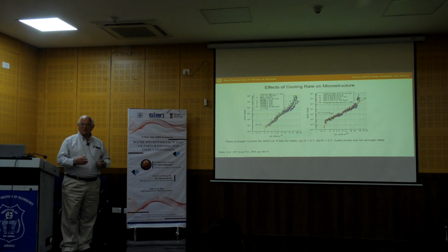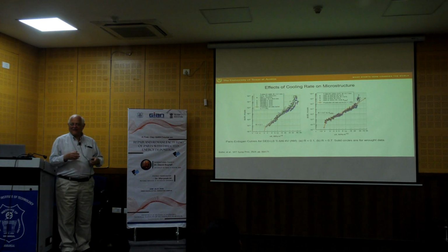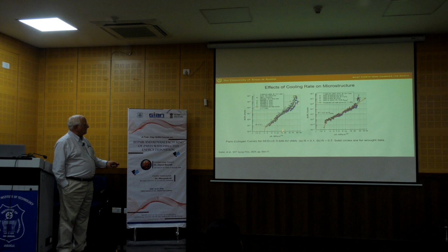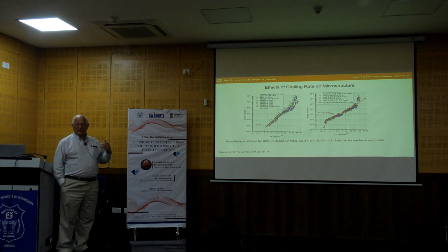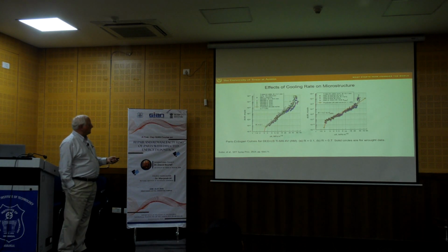And what that means is that the additive material has a higher crack growth rate, which is typically not what we like. We would like this plot to be very low and with a low slope, so we have slow crack growth, and it takes a long time to get the cracks growing.